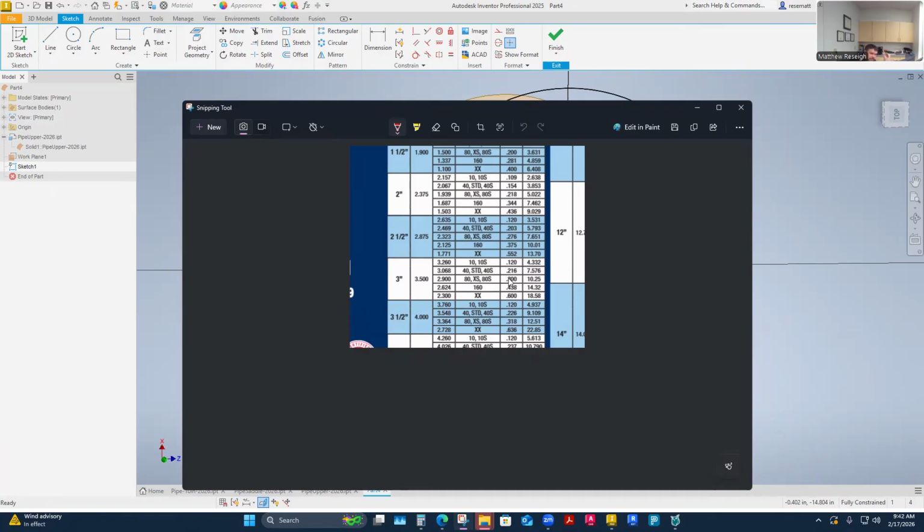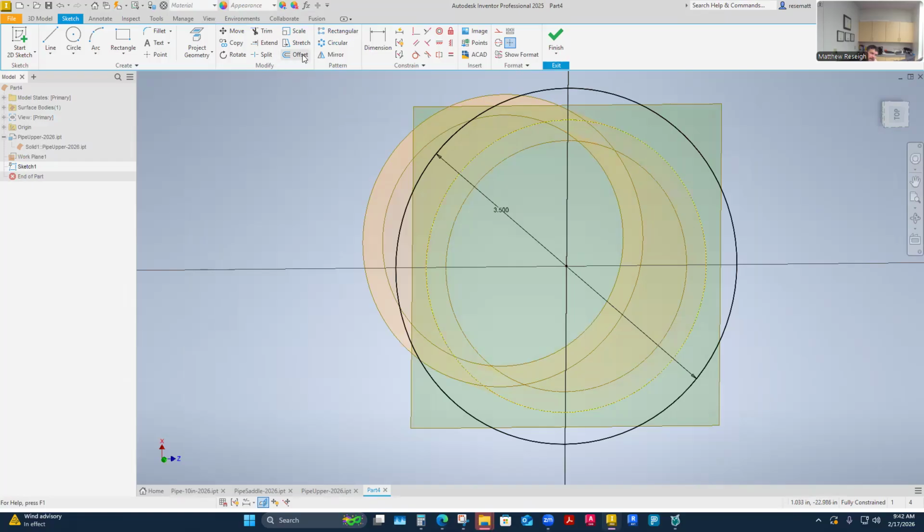That's different on sheet metal, but some of the same materials fall under the same sizing here in pipe, or different materials fall in the same sizing. So I'm looking at an offset of 0.216. Let's see how that works. I'm just offsetting this diameter for what actually 3 inch schedule 40 would be, 0.216 wall thickness.